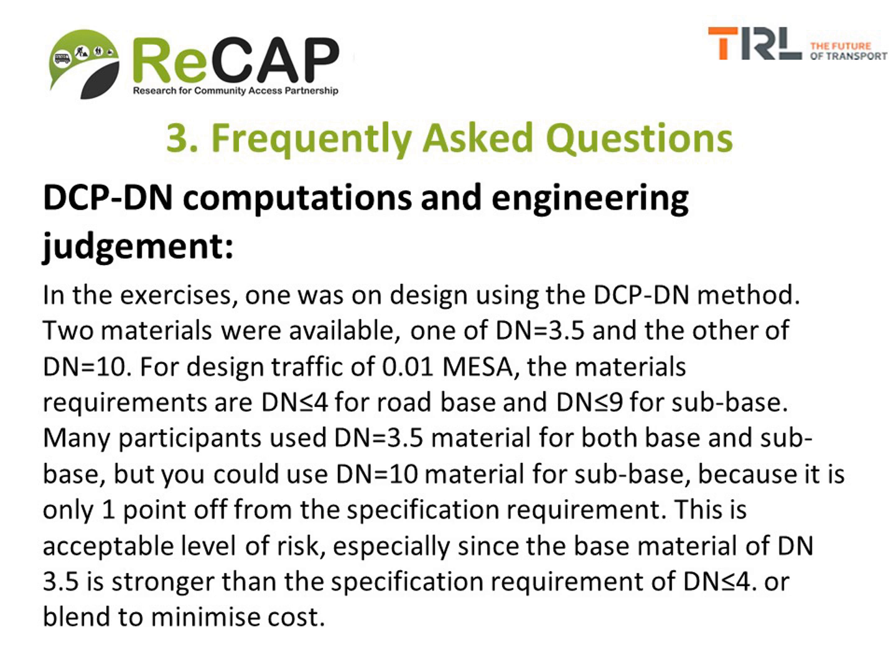And in this particular case, the questionnaire has said, can he use material with a DN of 10 when the specification required a DN of 9? That is a relatively minor change, and as far as we're concerned, that is perfectly acceptable, especially since the strength of the layer above it is actually stronger than the minimum specification. So you've got a little bit of a balance going on there. A small deviation in the lower layer from 9 to 10 would not be significant.